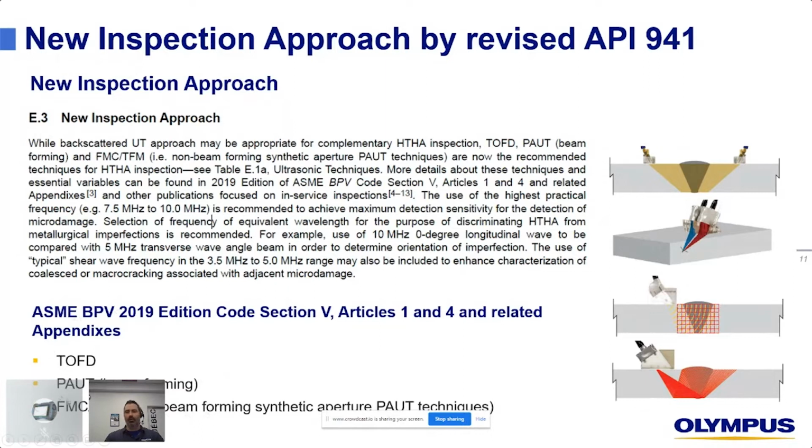What do they have all in common? They use the highest practical frequency, 7.5 to 10 megahertz, to obtain the maximum detection sensitivity and resolution for micro damage.